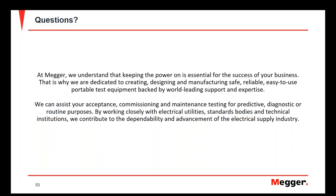Typically, the common test is to determine the pickup. So the instantaneous test will start at about 80% of the pickup value, and it will increase the current in pulses, giving a little bit of a delay for the breaker to cool down. The main purpose is to determine that pickup point. If it is instantaneous, it is assumed that the breaker won't take too long to trip.